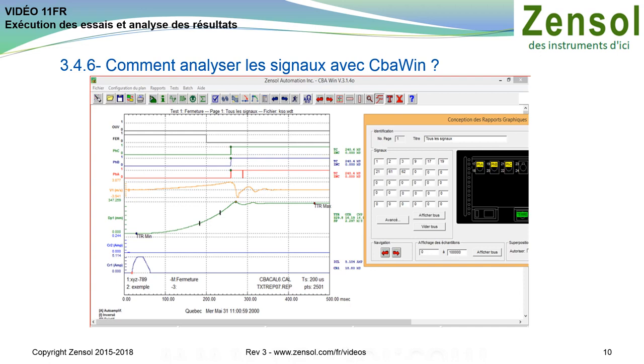Per test, you can have up to 10 different graphic presentations. CbaWin calls them pages. Use the red arrows to move from one page to the next, and thus from one graphic presentation to another. This is particularly useful for 24 contact circuit breakers in the 735 kV range to facilitate phase analysis. For example, in Hydro-Québec's standardized drawings, page 1 shows all signals, page 2 phase A, page 3 phase B, page 4 phase C, page 5 displacements, page 6 speeds.